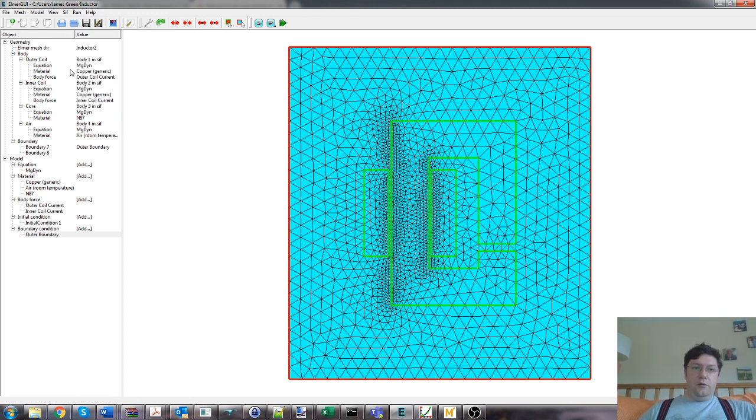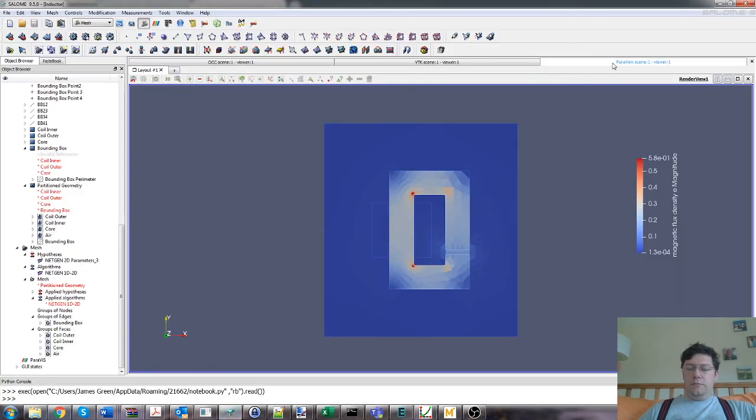And we can set up the solver here as well, or we can edit the SIF file, and if the problems become a little bit more complicated, we'll probably have to do that. And that we will go back to Salome. Oh dear, the dog's gone. To use ParaView to view the results.